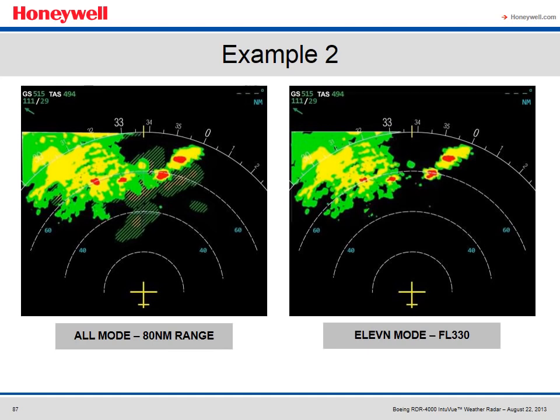And looking at an altitude slice at flight level 330, there appears to be a low reflectivity path for the aircraft to go through. In this particular scenario, it probably would have been easier and safer just to go around this line to the right, but it provided a useful example demonstrating how to effectively use analysis to determine a deviation path.